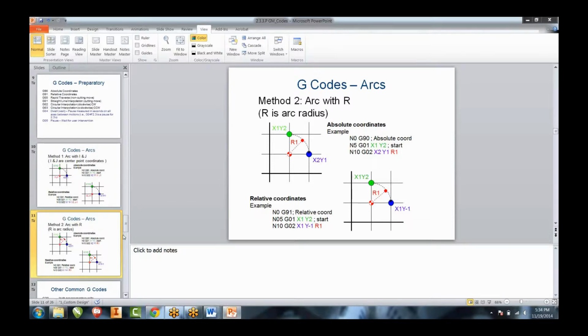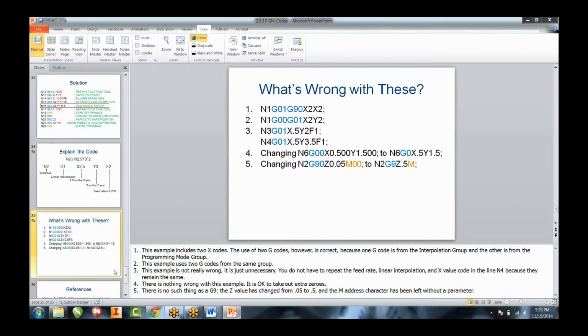And next time when we open up CNC Motion and you take a look, the kids will get the same errors all the time. Like if you're looking at this slide right here, look at any of these given lines. If you put a space, you talk about syntax and programming, if you put a space between the G and the 0, or between the 0 and the 1, that's going to cause an error. If you put a space between the 1 and the G, there's no problem with that, but that right there is going to be an error.